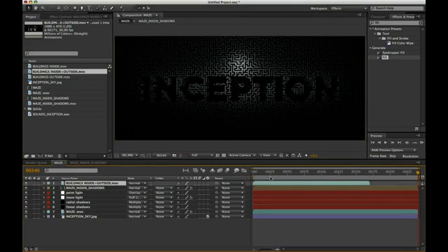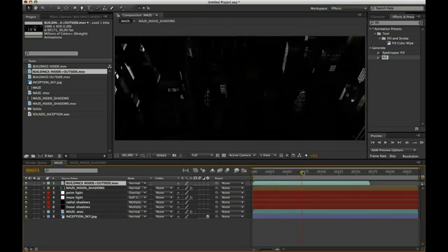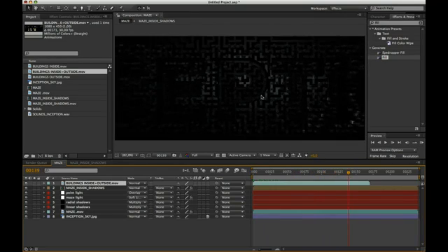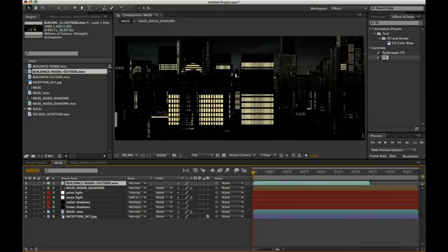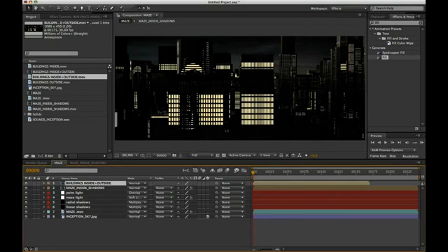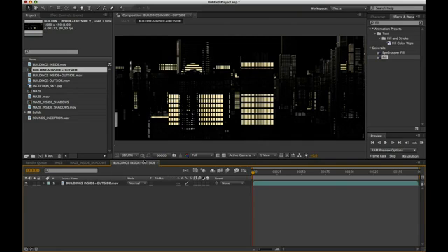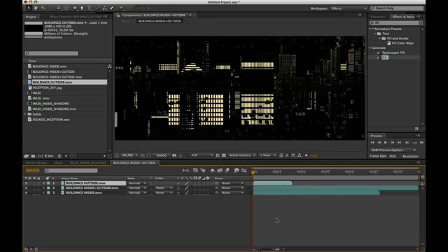Now drag buildings inside plus outside in our project. The animation of the buildings must have, for the inside and outside part, fading in different frames. To do this, create a pre-compose layer. Drag buildings inside and buildings outside. We set buildings outside at the end of the timeline.